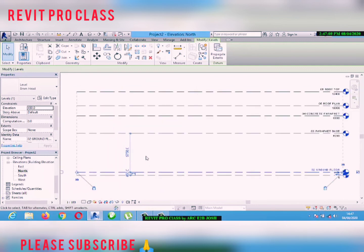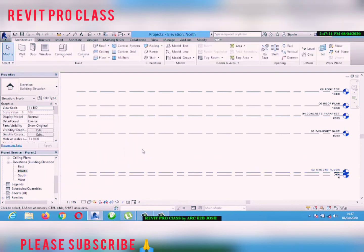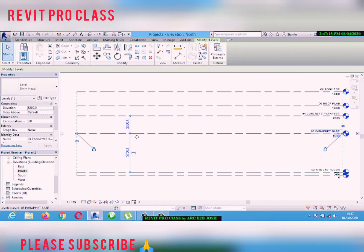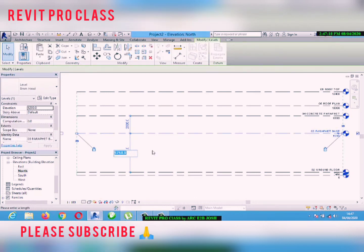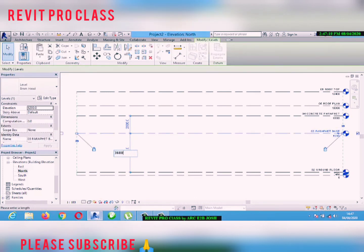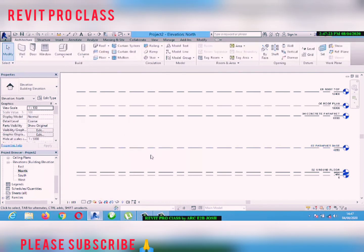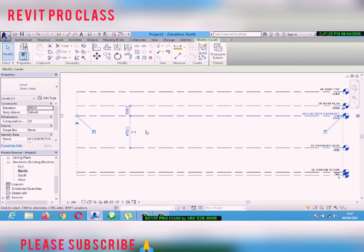Now you press escape, you click on the next level, that's the parapet level, you change it to the height of your building, 3600, you click enter, you escape. The next one is the concrete parapet. You are an architecture student, and you can use any height you want, but I used to use 600.